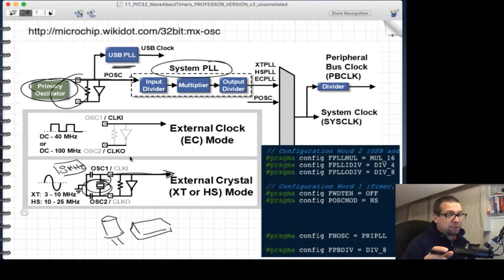And in a lot of microcontrollers, the USB signaling has its own timing path. They want to get an exact frequency on the clocking signal for the USB in order to make it work. So that's generally handled separately from the main pathway for the clocking of the board. Anyway, so you've got your phase lock loop.